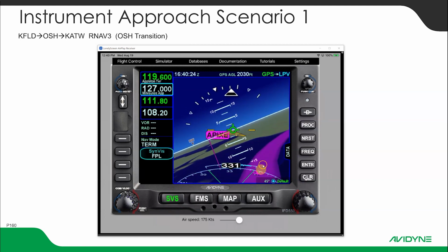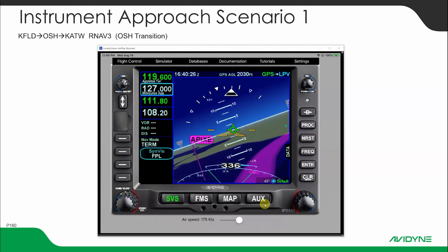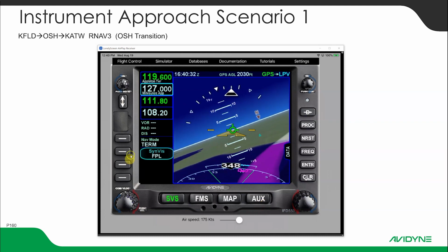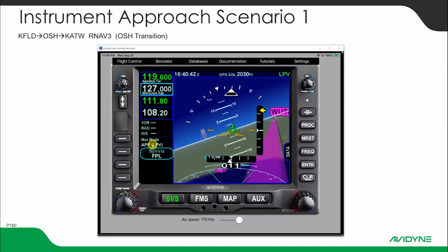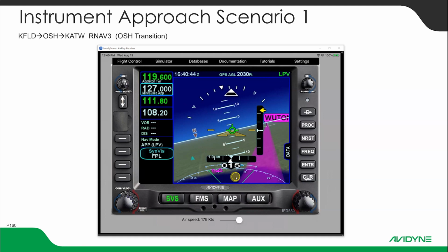Our lateral and vertical deviation indicators will appear, and we'll be fully coupled on our LPV approach. Our terminal mode's going to switch to approach mode. There it goes. Well, I'm now in LPV approach. I've got approach mode here and my nav mode, and now I'm inbound.